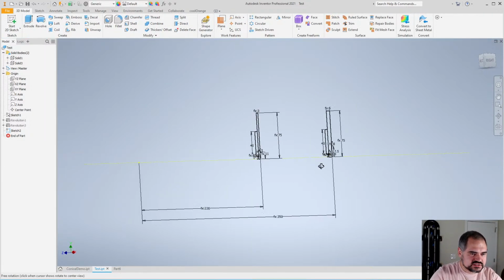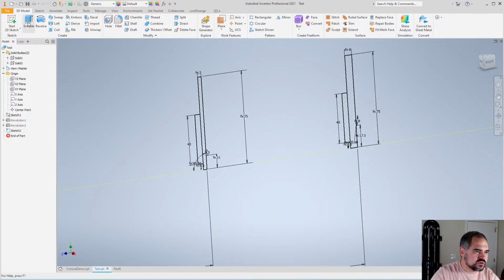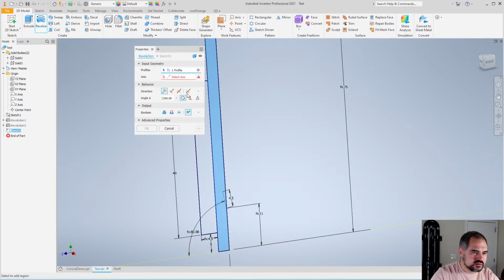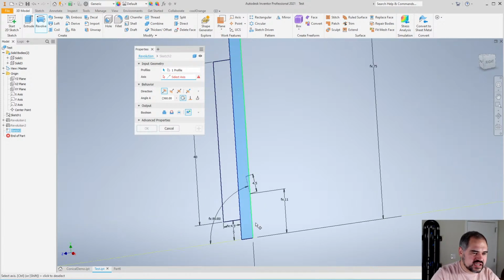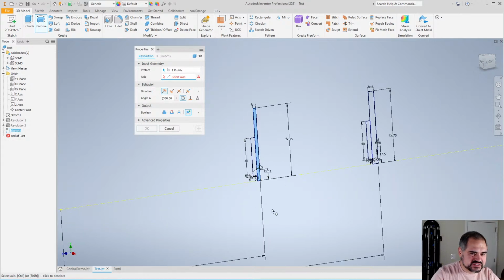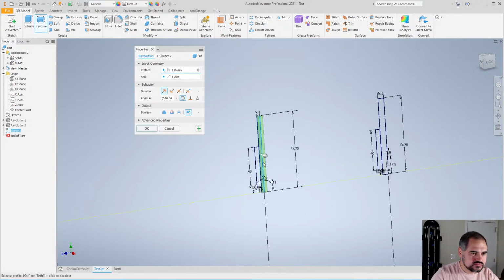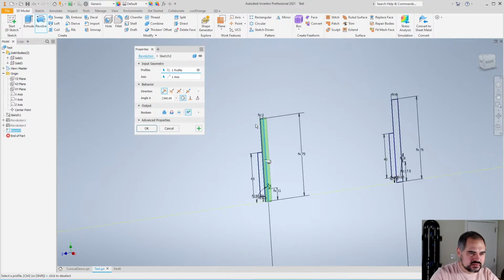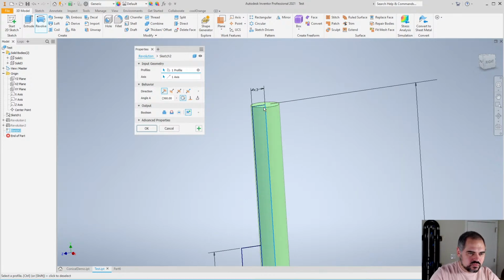So now let's create our tone holes. I'm going to revolve. So tone hole 1. Select the profile. We're going to rotate it around the axis that defines its position, and make sure that it's creating a new solid rather than merging with one of the solids we already have. And that will be everything we need for this tone hole.